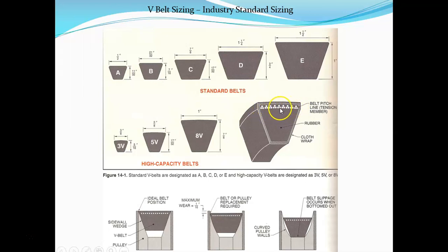different configurations of these. These are little three-piece fiber cores put together along the top edge of the belt. And you can see the ones at the bottom that have the fiber core. That is the strength of the belt. So if you damage the belt or damage the fibers, then it's likely to break. Your strength is not coming from the filler material, the rubber, or the outside cover.